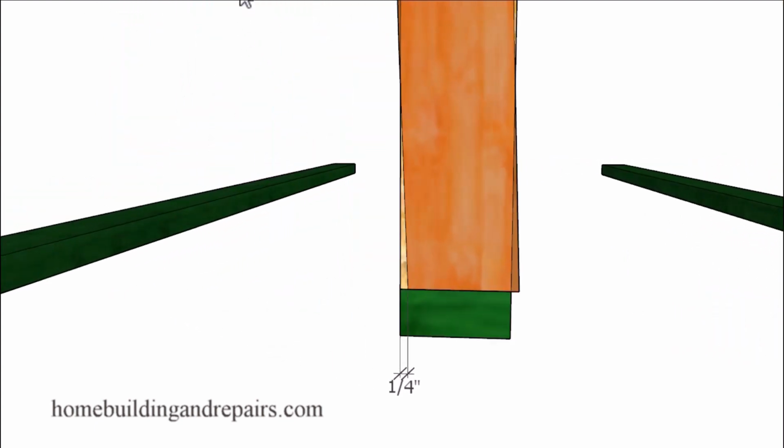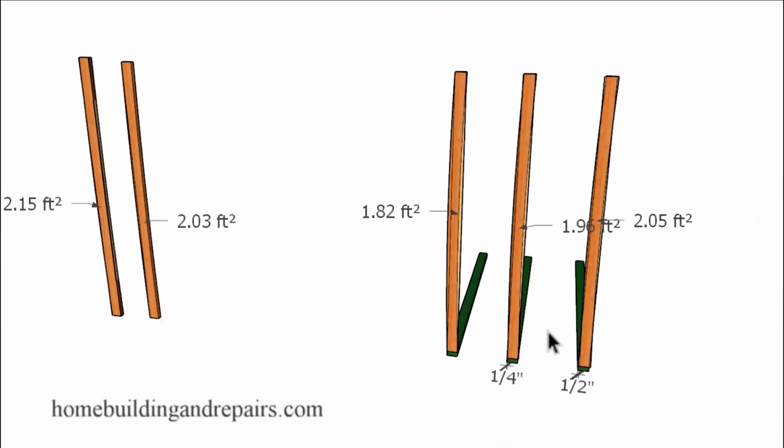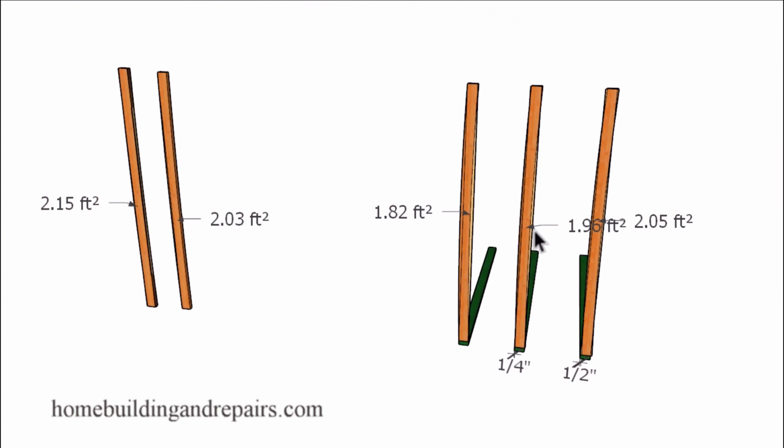My guess is that most people are going to remove a wall framing stud with a 1-inch bow in it and replace it anyway. And for those of you who are not going to do that, let's just take a look at the numbers right here. They don't lie. You're going to benefit because this method is going to provide you with more surface area for the existing wall framing stud, providing us with a better method for building.